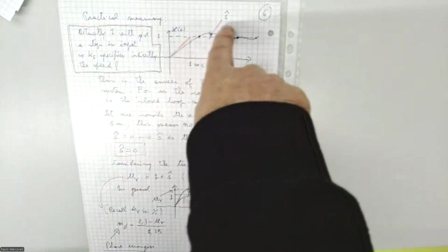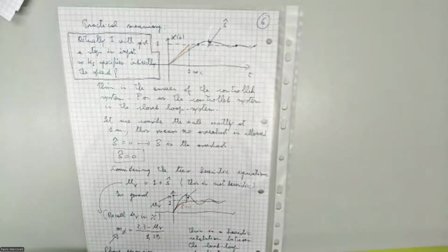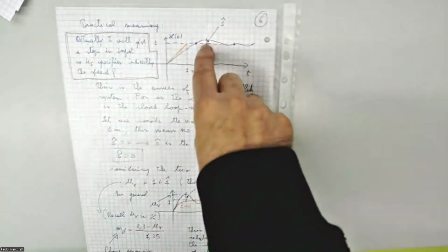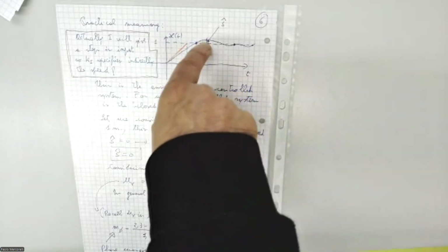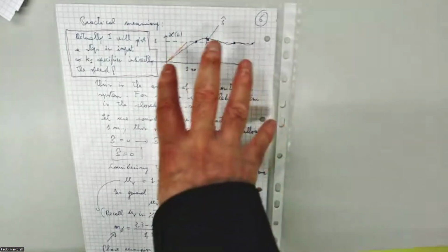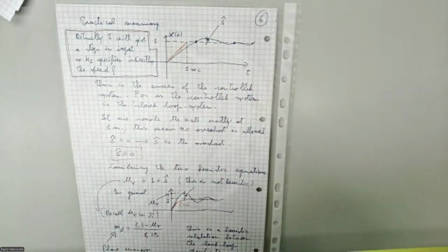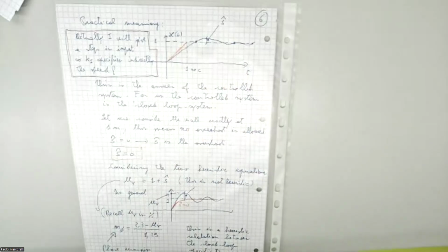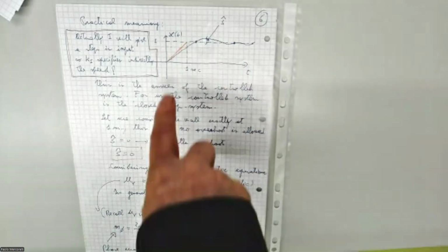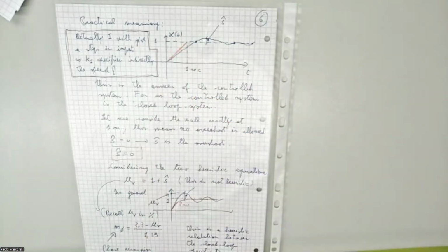The risk is that I will exceed 1 meter by more than, for instance, 10 centimeters if the sensor measures 10 centimeters. This means we have to guarantee that the maximal overshoot, the maximal error, is not more than 10 centimeters, 0.1. And this is guaranteed by G(s). Of course, I try to brake the car a little bit, in the sense that the controller will renounce this 1 second a little bit, as we can see. And this is the task of G(s).